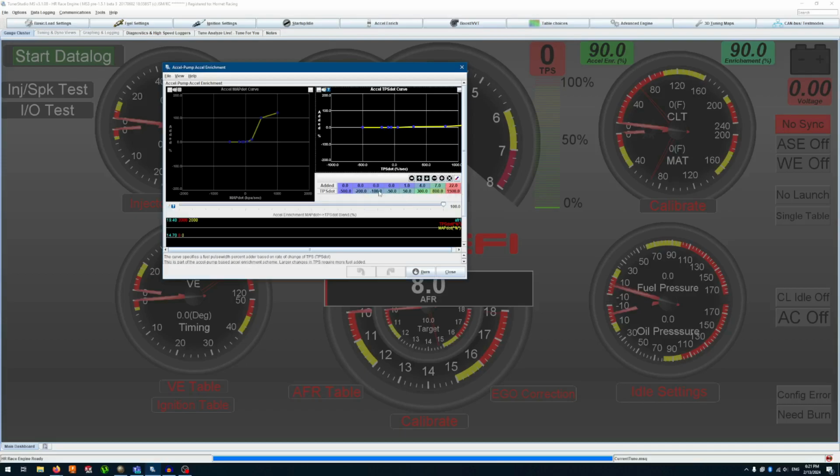If you're really lazy on throttle, as in you're trying to rev it and it's just not happy, you could try and adjust this. Just try it out, test it. It's not going to really hurt anything. Understanding TPS dot is not intuitive, obviously, because we don't really understand that, but it could take some testing and stuff, and that might help you.